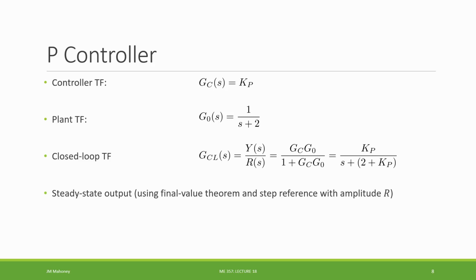And the closed loop transfer function, and this is going to be true for all of the systems we're going to look at, because we're assuming we have a perfect sensor and a perfect actuator, they're just 1. As we've seen from all the previous examples in this unit, the closed loop transfer function will be our controller transfer function times the plant over 1 plus the controller transfer function times the plant. I did all of the algebra for these examples in the associated Mathematica notebook file, so I'm just including the results here, but this is all done algebraically.